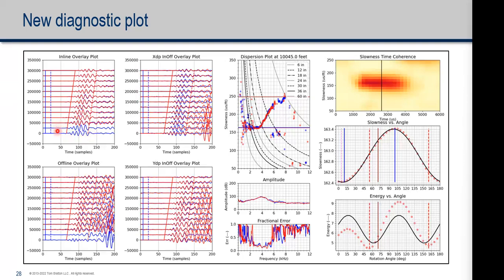Because the transmitters are not co-located, they're about a foot different, the only co-located waveforms I have are a subset. On the Sonic Scanner, I've got 13 waveforms, so there's 11 that I can use for the four component analysis.